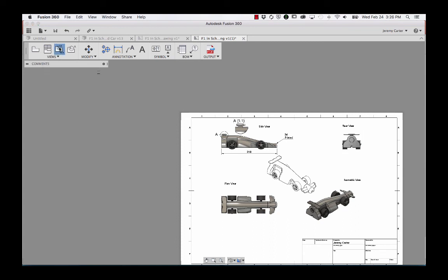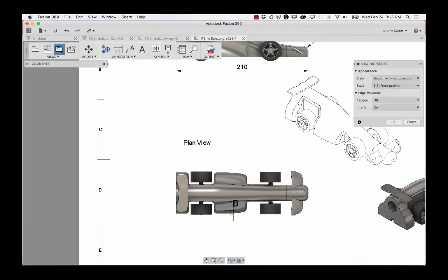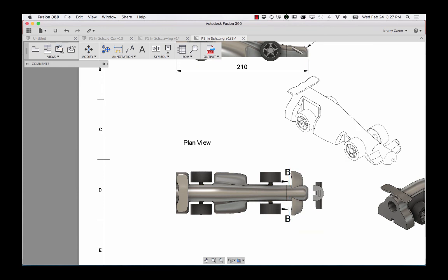This allows you to view cross-sections. Click the view you want to do a cross-section of. Click to start and end the endpoint of the cross-section. It will only be a cross-section this length of the line. Right-click, drag out your section, and press OK to finish. These can be dimensioned too. Use all of these techniques to put the main dimensions to show your car complies with the rules, and save your work.